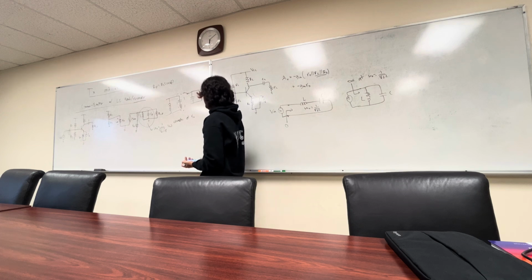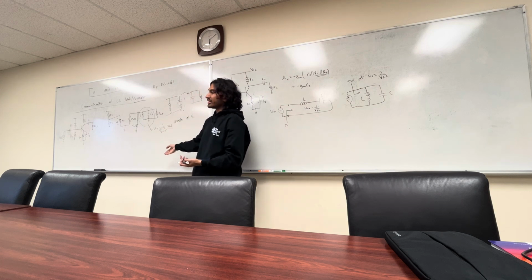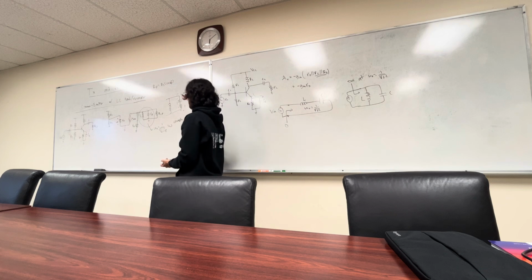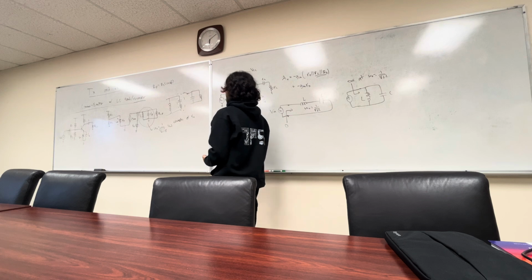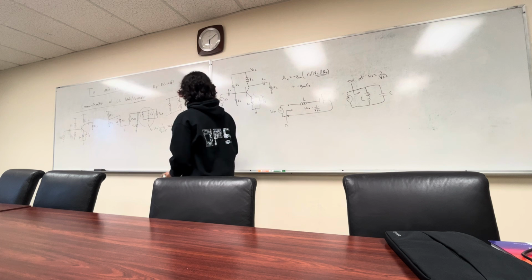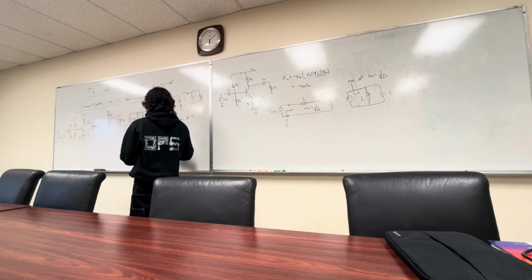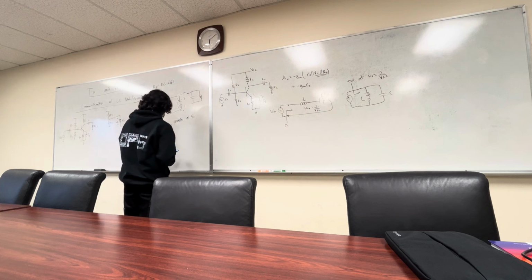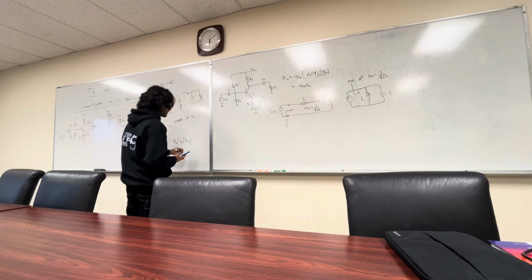Yeah, sure, but then of course any loss is going to cause some resistance, RLP. It'll be in parallel with R naught, and a parallel operation is not like a linear operation. So even though the RLP might be really large, 100,000, that's going to be in parallel with R naught. So it's not a direct translation, you have to be careful of that. And if we do all of this out, ideally our gain is negative GM times R naught parallel with RLP.